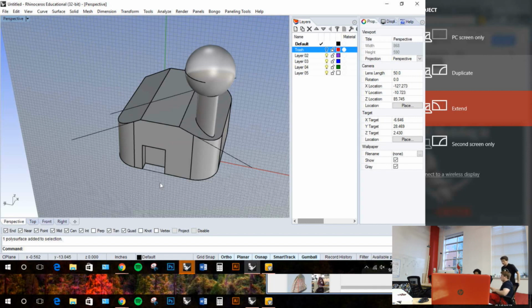So, have you done the door so far? No. Okay, so let's do the door first. So select those, and the bottom one too. Or actually, you want to close that up. So we've got to backtrack a bit more. Draw a line closing up that square, and then select all four of the lines. You can do that by dragging a window like that. And just type join. Okay. And now you can extrude that.